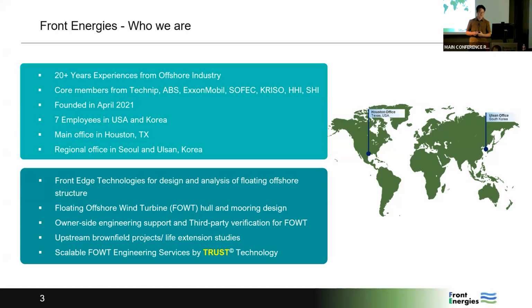two very outstanding technologies. One of them is the time domain structure analysis technology. This technology is very important and necessary for the floating offshore wind turbine structure, because the floating offshore wind turbine requires time domain structure analysis to assess the fatigue life estimation. The floating offshore wind turbine structure is governed by fatigue, so they want a very accurate assessment of the fatigue life. That's why time domain structure analysis is required.